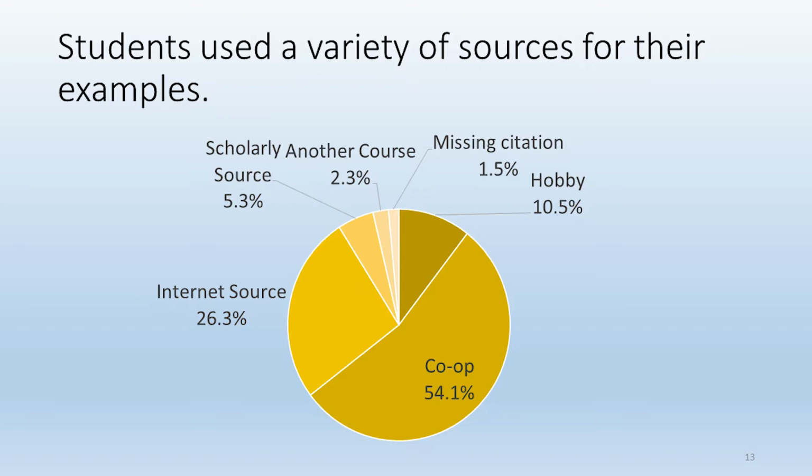But in the oven for curing metal, there are really tight tolerances, and in those cases, you don't have the right properties if the temperature varies more than 2 degrees from its set point for very long periods of time. So while they're both ovens and both controlling temperature, it creates a really great discussion in class about requirements and design for control systems.